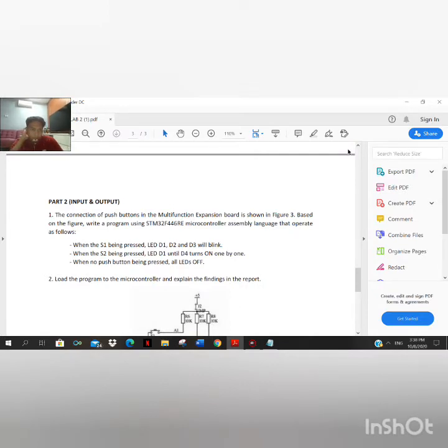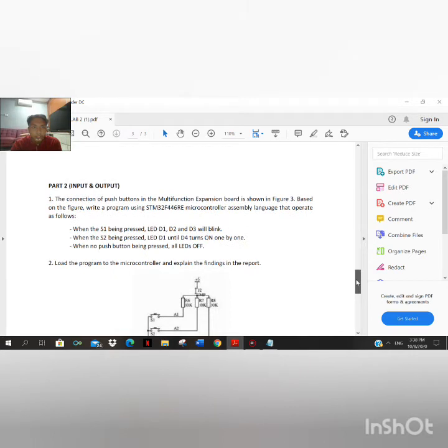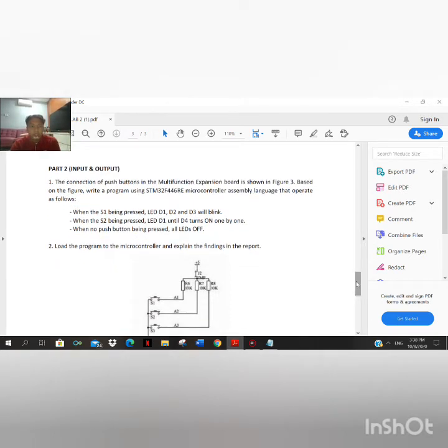Assalamualaikum. My name is Hariz, and I'm going to explain about part 2, about all the codings. Okay, as we can see, we were asked to do these three conditions, where the first condition is when S1 is being pressed, LED D1, D2 and D3 will blink, and when S2 is being pressed, LED D1 until D4 will turn on one by one. And the last one is when no push button is being pressed, all LEDs are turned off.